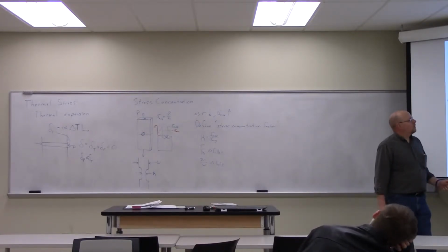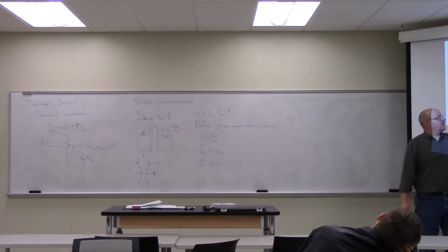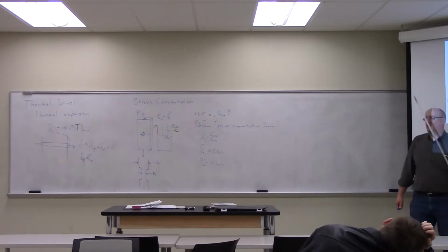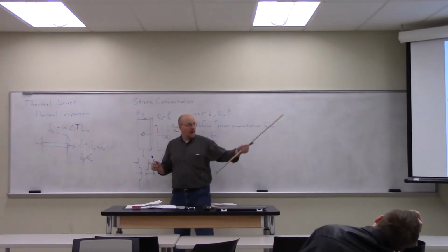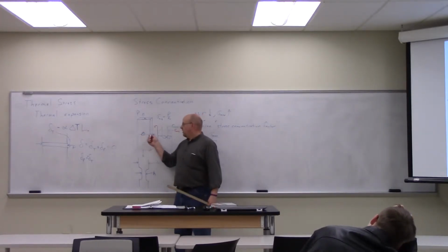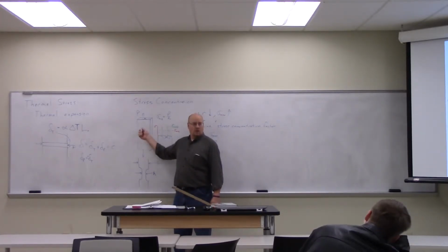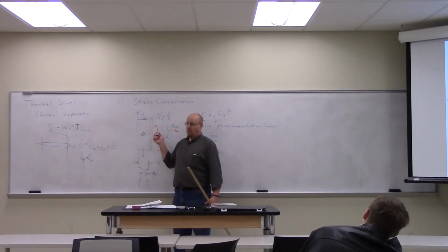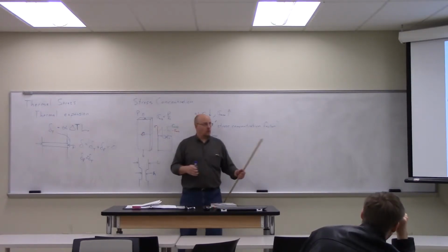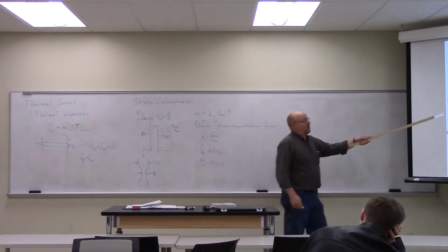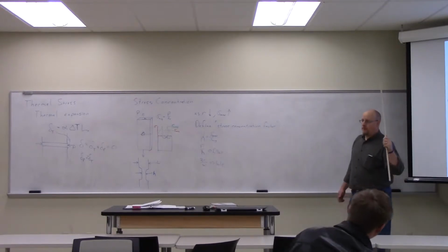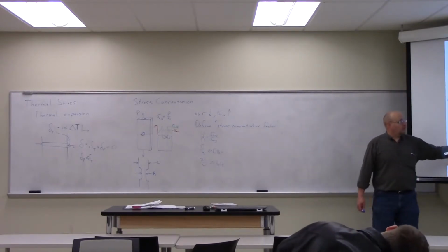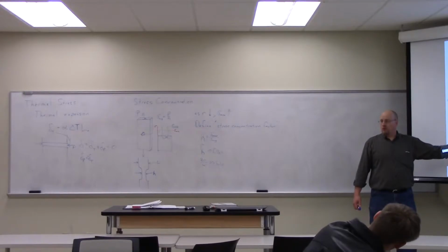And here, the average stress is defined in terms of the cross-sectional area at the hole. So in other words, they've already taken into account on the graph the reduction of cross-sectional area that resulted from the presence of the hole. Okay, so that piece has already been taken into account. And yet still, there's a concentration greater than 1. And you notice most of these are 2 for the hole. Most of them are greater than 2.